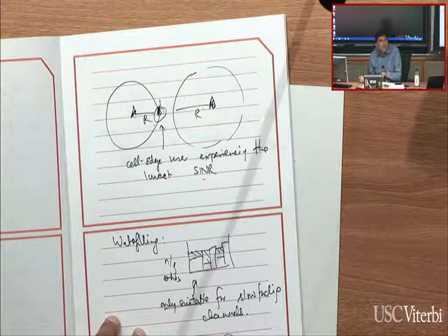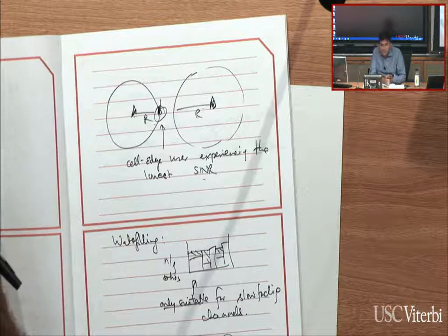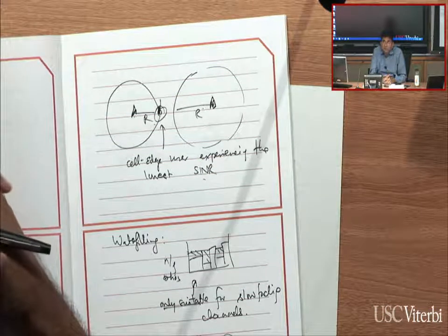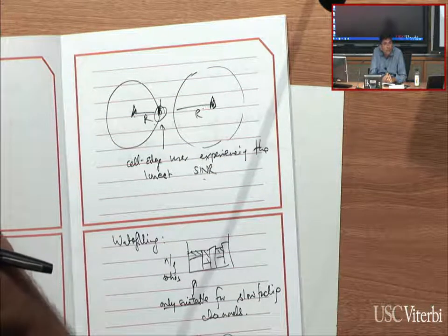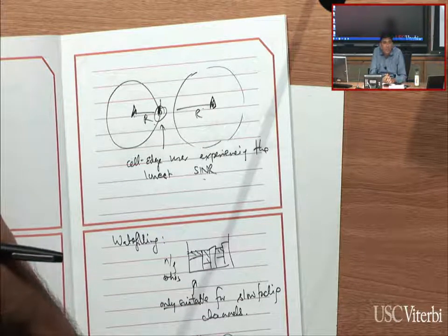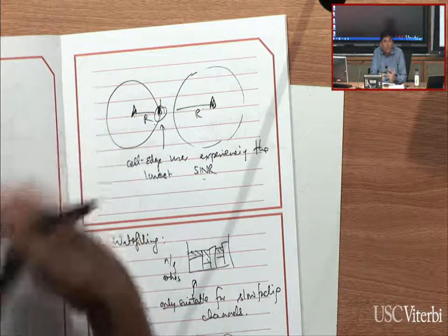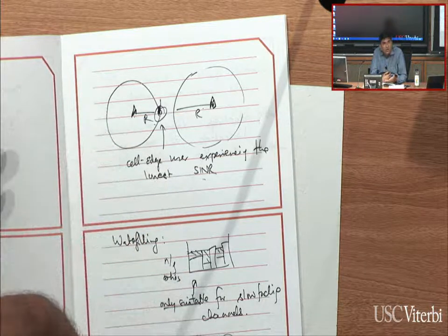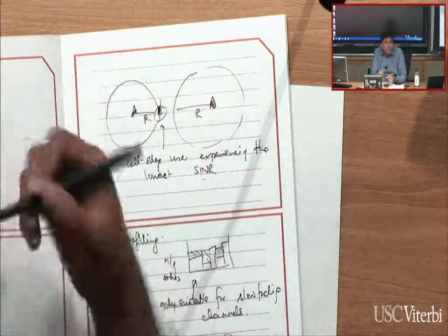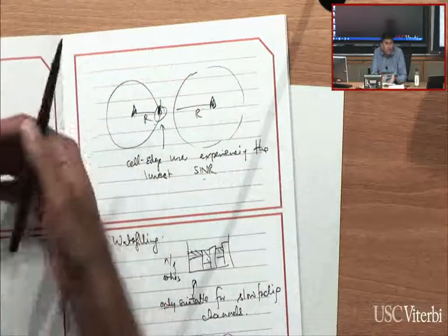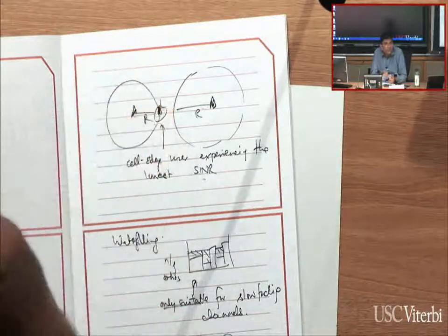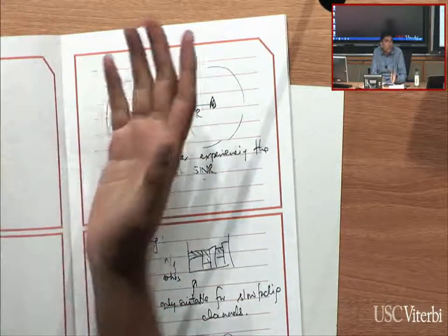Right? And in wireless networks, as we're going to higher and higher, I would say, dynamic environments. So if I'm going to put my radios in cars that are talking to other cars, talking to things on the roadside, just as an example, the velocity is now very high. So a car that's driving at 20, 30 miles per hour, talking to some base station, that link quality is changing on the order of microseconds. And so that's typically faster than even a packet could be sent. So when you're sending that packet, what that gain to noise ratio is going to look like, you have no idea.